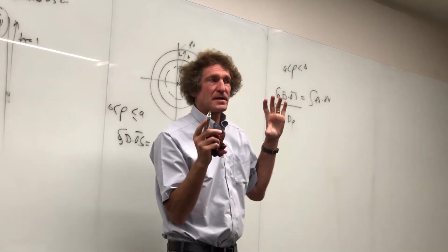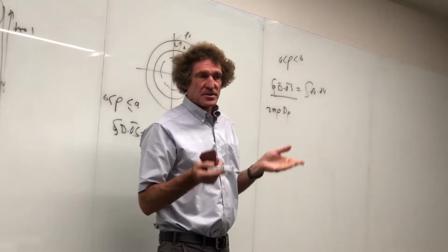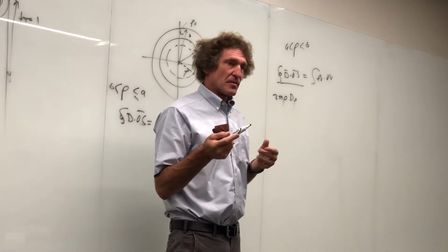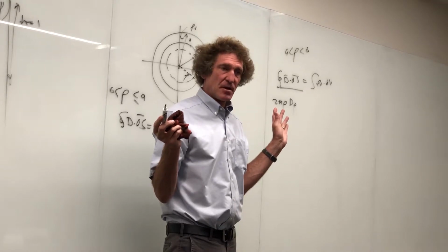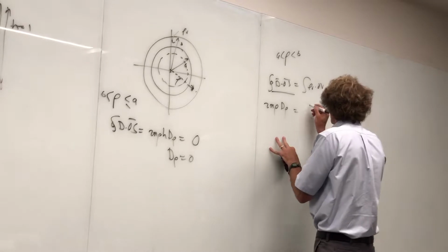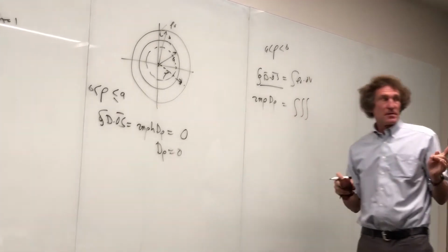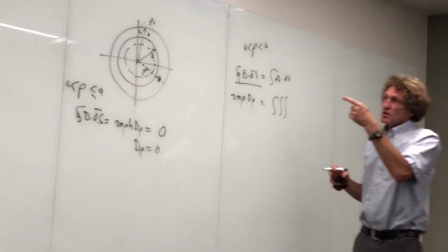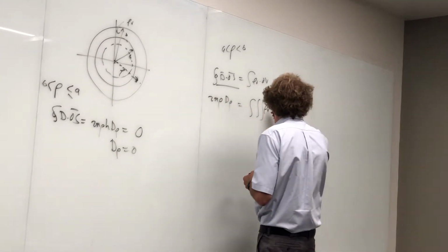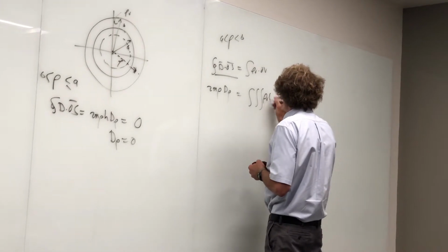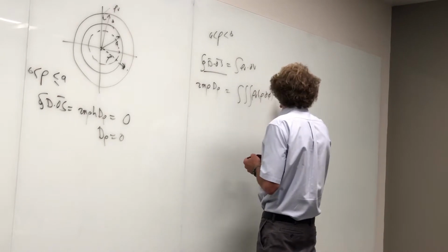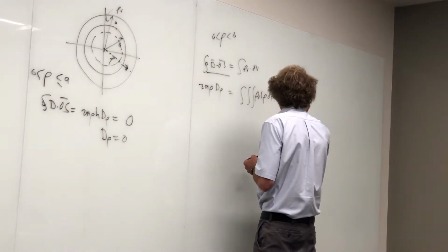We don't have to keep writing that over and over again and doing the integration, the rho d phi dz, and then integrate over the limits. This is what it is. It's the surface area of the outer part of the can. On this side, it's going to be equal to what? Well, this is a volumetric integral, technically. And it's the charge density, which I'm just going to leave as rho v for now, because it's a constant. And the differential unit of volume in cylindrical coordinates is rho d phi, then d rho, and then dz. Does everybody agree with that?